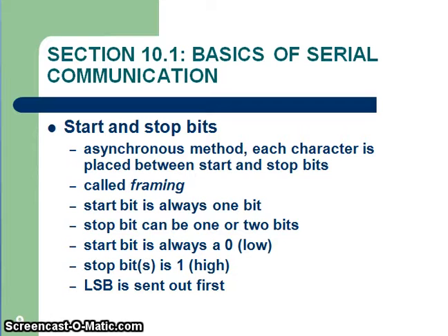In the asynchronous method, each character is placed between start and stop bits. A combination of data and stop bits is nothing but framing. The start bit is always 0. The stop bit is always 1, and it can be 1 or 2 bits, or 1.5 bits.